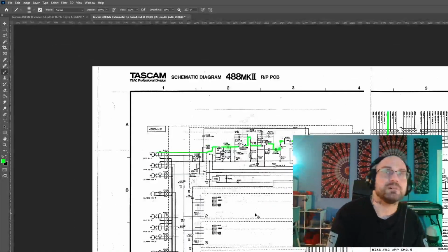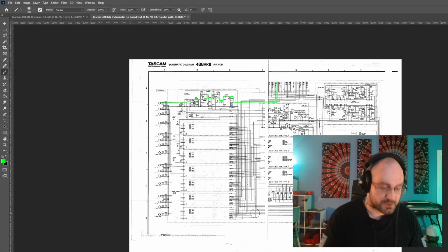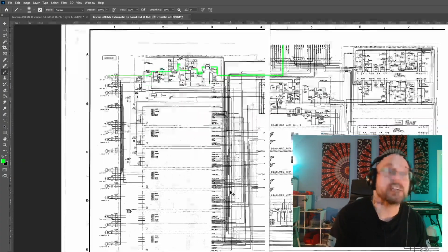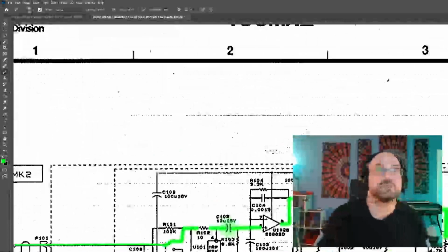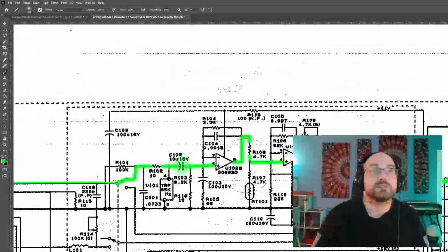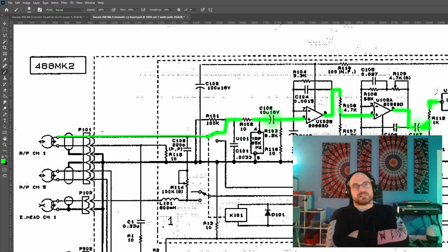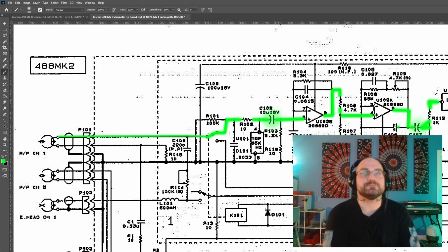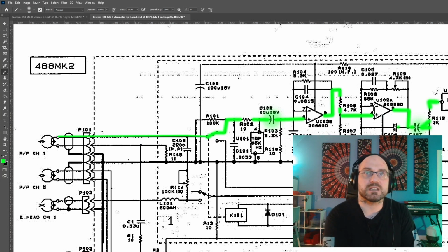I mean, how many components are on there? I don't know, I'd guess hundreds. Anyway, at least 200, maybe 500 components. But actually, when it comes down to it, if we've got one dead channel, let's say it's channel 1, there's only 1, 2, 3, 4, 5, 6, maybe at most 8, maybe as few as 6 places that we're going to test in order to find out roughly what's wrong before we can start sensibly replacing things and hoping for a solution to our problems.